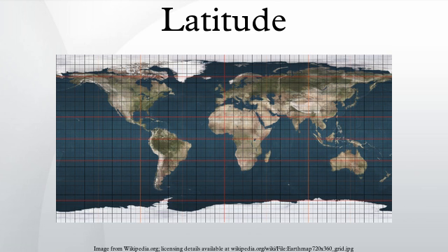The terminology for latitude must be made more precise by distinguishing geodetic latitude, the angle between the normal and the equatorial plane. The standard notation in English publications is φ. This is the definition assumed when the word latitude is used without qualification. The definition must be accompanied with a specification of the ellipsoid.